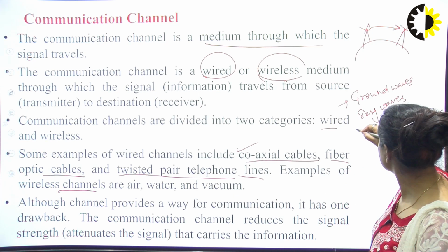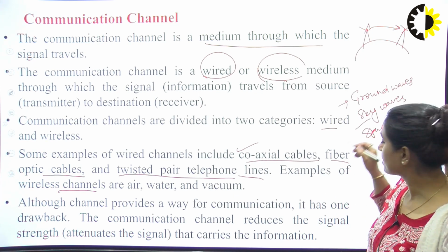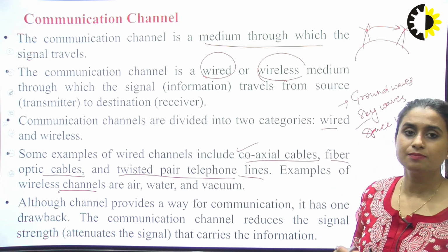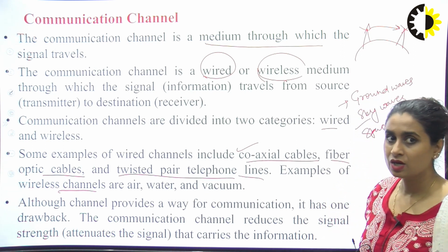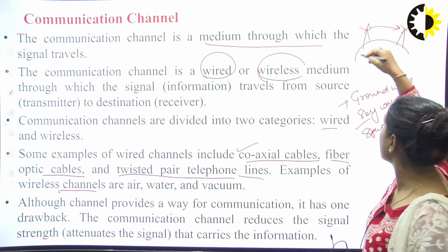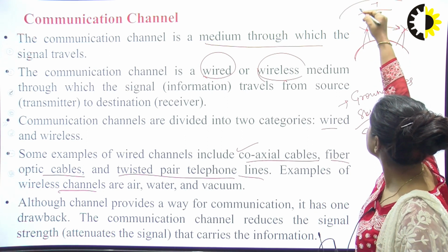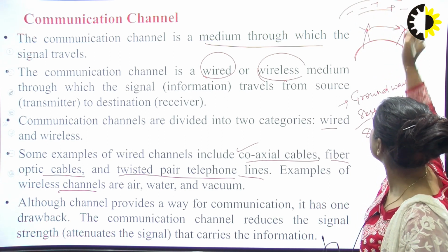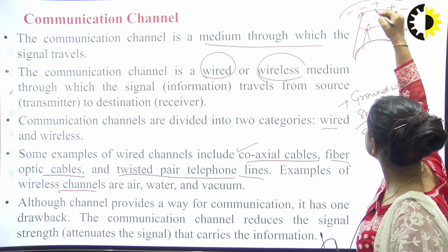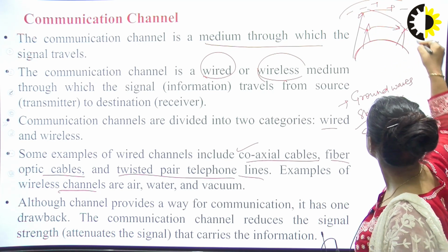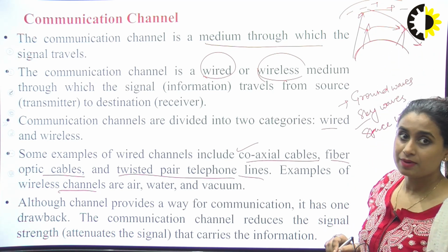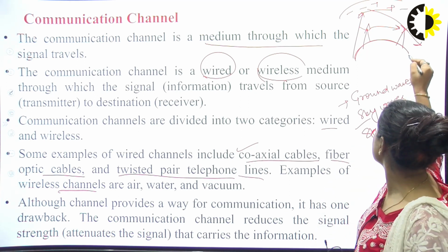After that, we have skywave communication, where the signal propagates in the megahertz range, right? Around the Earth we have the stratosphere, troposphere, then the ionosphere. These have highly dense ions. When we propagate a signal in the megahertz range, it is reflected back by the ionosphere and received at a farther distance.